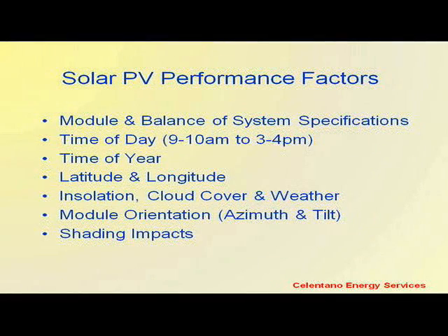What are the factors that impact your electricity production? Well, you have the module, the type of module, its specifications, whether it's crystalline or polycrystalline or monocrystalline, whether it's got microinverters or regular inverters. Also, of course, the time of day. When the sun is high in the sky, you're going to get more production. The time of year: you're going to get longer days in the spring and summer than in the autumn and winter. Your latitude is going to affect it. The farther north you are, the lower the sun will be in the sky.